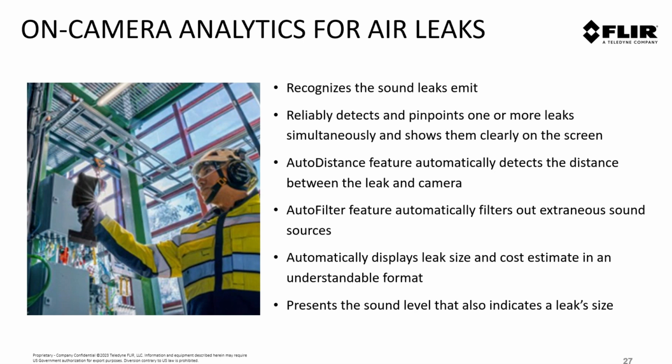So 16 to 20 feet is kind of a max solid recommendation, where you're going to find about 90% of those leaks that are detectable down to 0.004 liters per minute leak rate, which is a very small leak rate, and that's at 0 atmosphere. But ultimately, distance is really going to be relative to the size of that leak. So hopefully that answers that question.